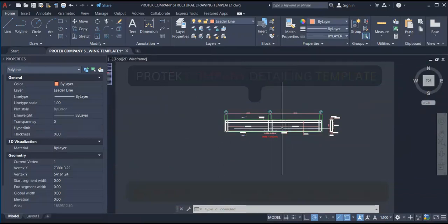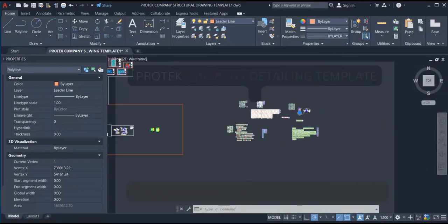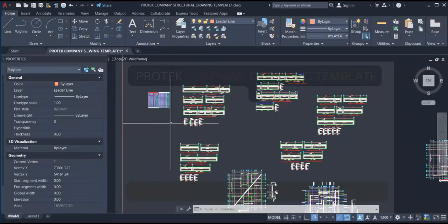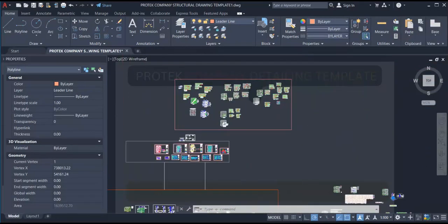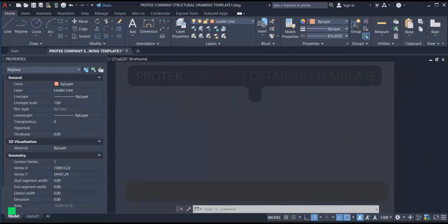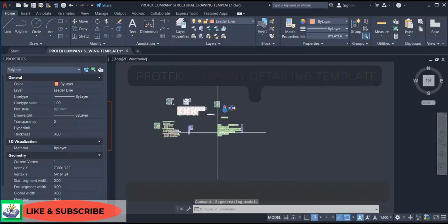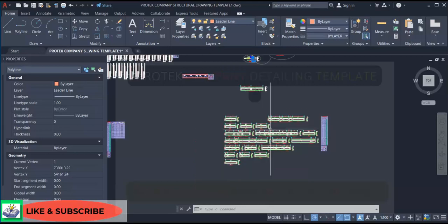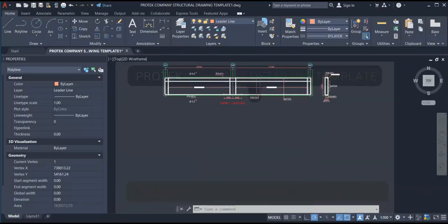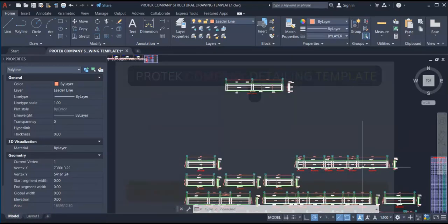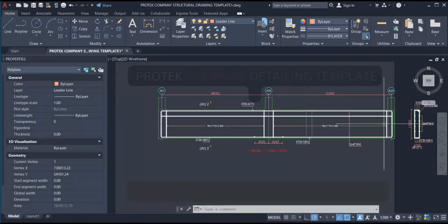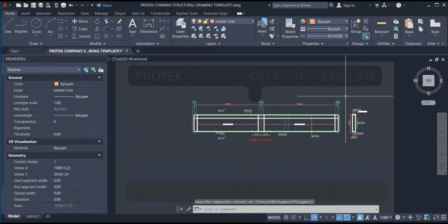With this template, you just have to come over to these provisions. There are ground beams here. You copy one of these ground beams and its sections, and take it over to this provision where you have the ground beam you imported from Prokon Structure. Then with the help of that ground beam, you will be able to edit this new one successfully. Once you are able to edit it just like this, you will also proceed to identify this beam on the ground beam layout.